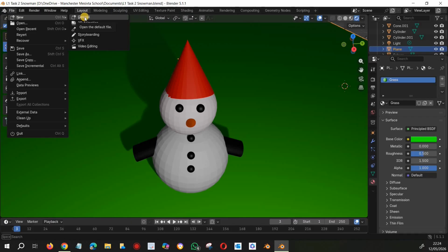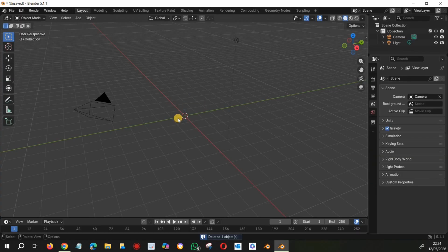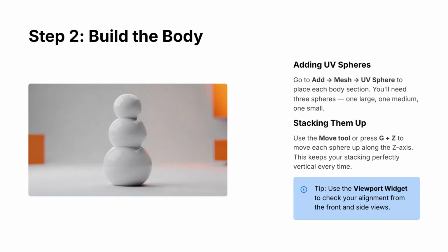First, launch Blender, then File, New, General, and what we need to do is to clear our workspace. Remember to delete the default cube by left-clicking it and then pressing X, and then delete. Make sure you switch to rendered mode, so again, like the last time, up in the corner, the rendered circle, which is in the viewport shading section. And this will be so that we can see our colours and lighting as we go through our work.